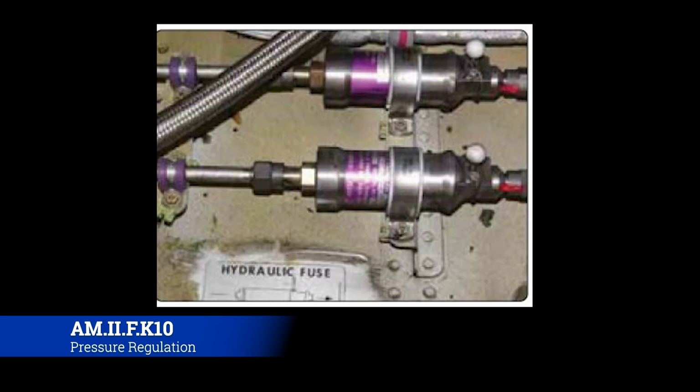Okay, so another neat device is a hydraulic fuse. What a fuse does is allow the system to be closed off if there's a sudden downstream drop of pressure. Say 100 psi is the regular operating pressure for the hydraulic system. If on the upstream side the pressure is still at 100 psi, and on the downstream side it all of a sudden drops off to, say, 80, the hydraulic fuse closes and preserves that system.